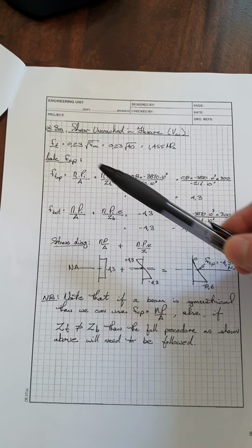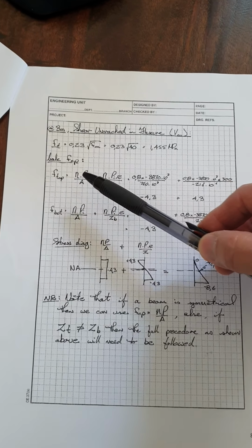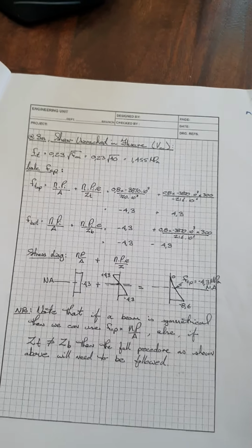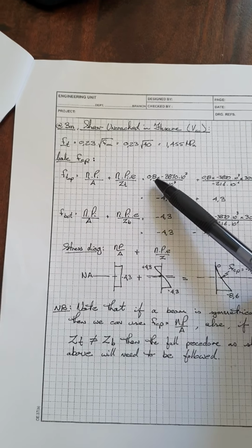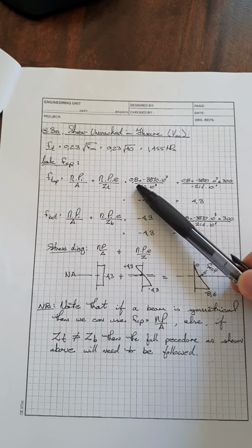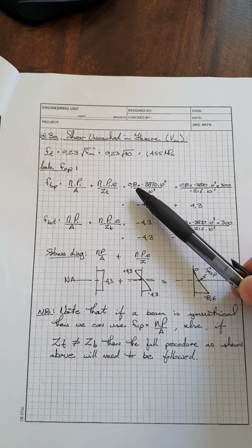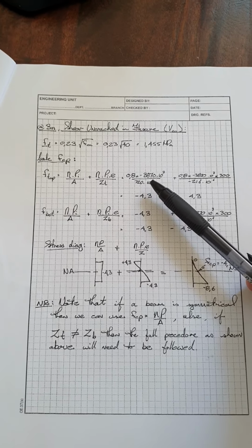That is the effective pre-stress. So eta times P over here is the effective pre-stress, in other words. In this particular case, we're working to an eta factor of 0.8, in other words, a 20% loss at 3 meters along. And that's how we're working this particular example.